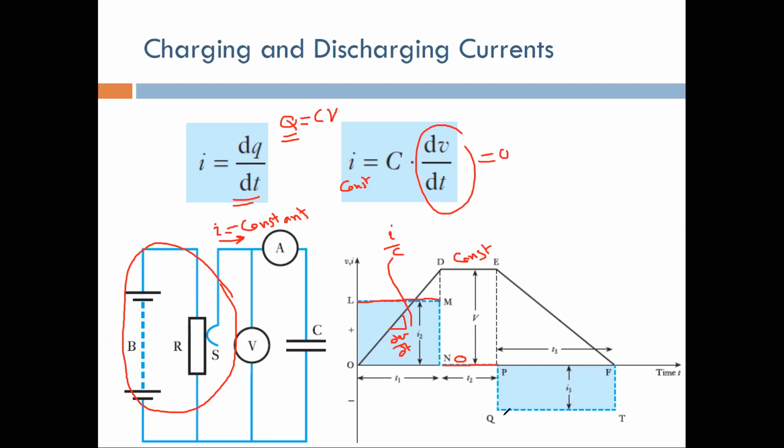If you change the current to be negative, basically dV/dt will be equal to I over C. Since I is negative, the derivative will be negative, so the slope of the voltage will be negative. It's going to keep going down like this. If I turn off the current when the charge is 0, then it's going to stop with 0 charge and 0 voltage on the capacitor. Is that clear?